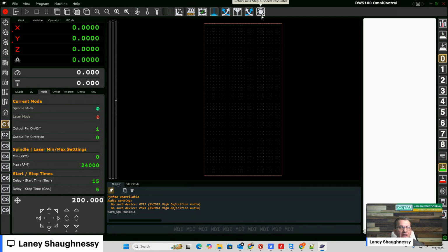And you'll notice they have the same icons across the top. And the icon that's missing is the one icon with the rotating spindle, which is dedicated to that 2440. So that's the differences between the profiles as far as the look and all the buttons and features. Everything else is the same except for the menu on the right will change depending on if it's semi-automatic tool change or fully automatic. And then the menu across the top, those buttons will change only by the one icon if it's 2440 versus the other machines.